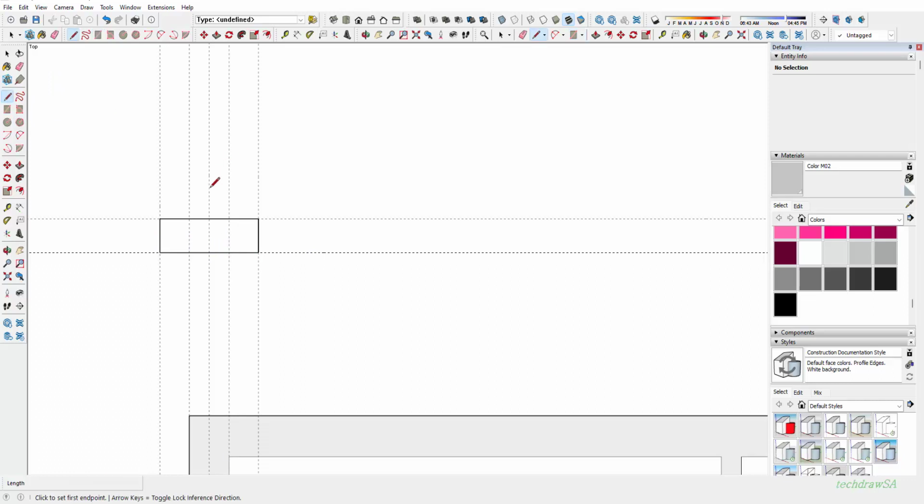Once we've done that, we're going to do our projection straight up from there to show the external line. We also will need to read our question to know what is the distance from the top of the foundation to the bottom of our hardcore, whatever distance that might be. Let's just say it's 400, and that you will get from your question paper, and then you will also know how high is that hardcore, and let's just make it about 120 millimeters, and let's say the concrete surface bed is going to be 120 as well.